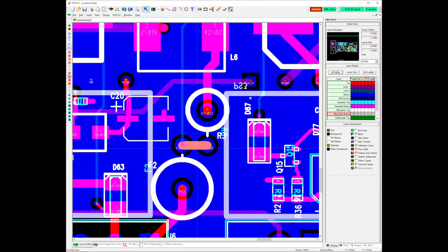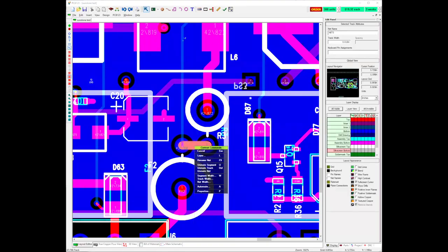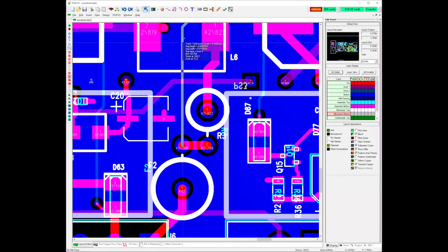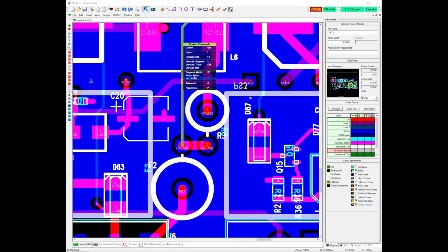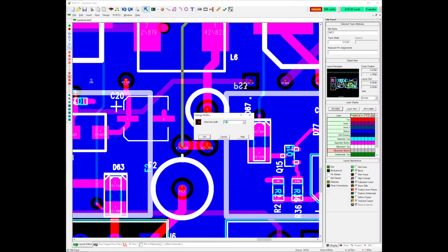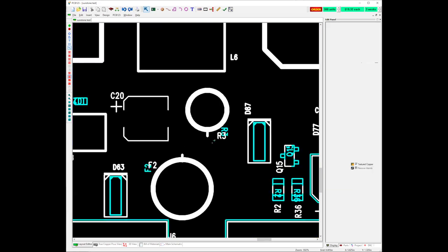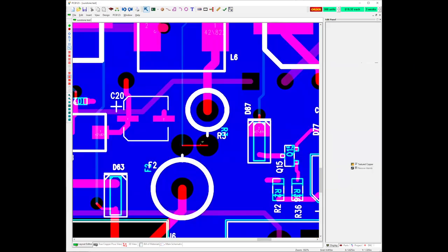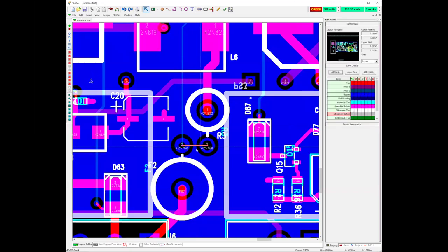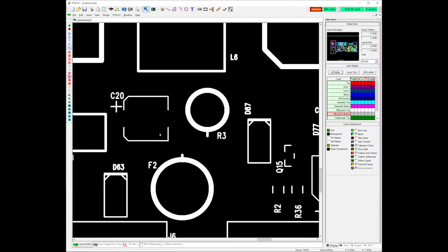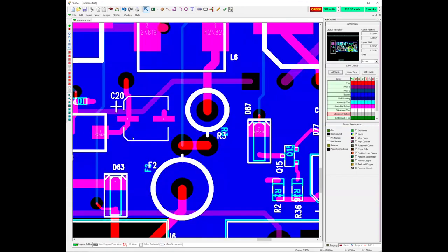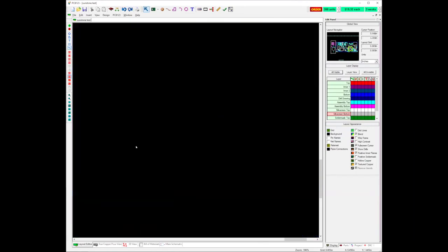This is the path here. But if I change the net width here to something like 8 mils because I want to just route a sense line, it changes this current path as well, and I don't have that. You don't see it happen. It's off the screen, so you don't catch it until you get a puff of smoke when you plug your board in, and then people ask you hard questions.